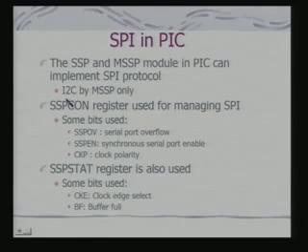MSSP can be used for implementation of I2C also. So, in fact, using a PIC, if you are using that version of PIC which has got both SSP and MSSP modules, you can set up an I2C bus, connect a set of peripherals via the I2C bus, as well as connect specific devices via SPI protocol using maybe the SSP module. When there are a number of IO devices to be connected, you can adopt this kind of architectural model.